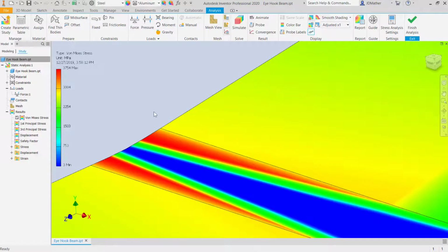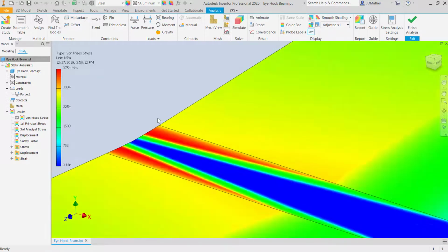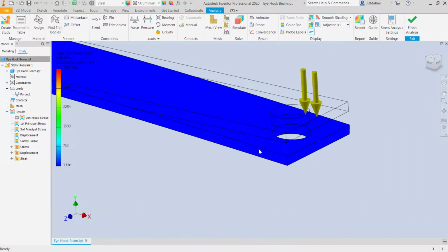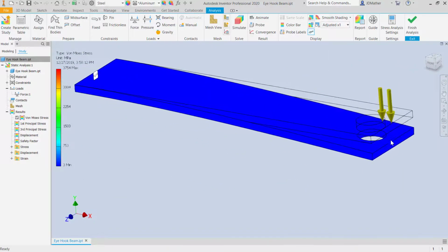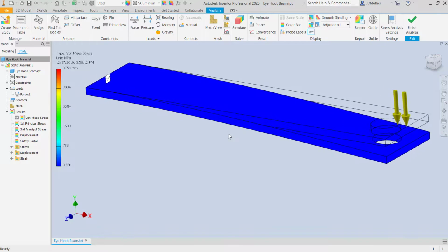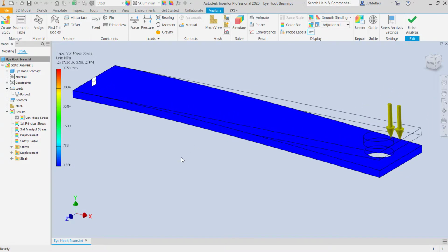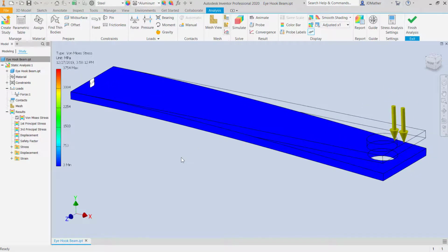So we have a high force divided by a low area, and we refer to that as a singularity. We know that that isn't really something that is a problem for our design, so you have to watch out for the introduction of singularities like that.